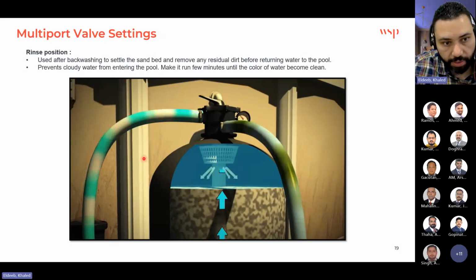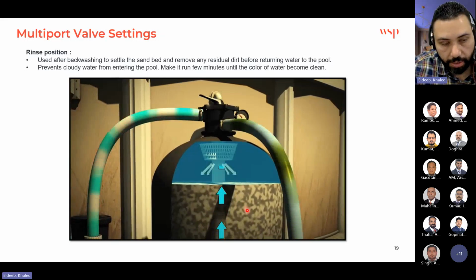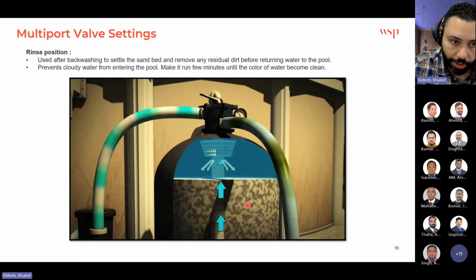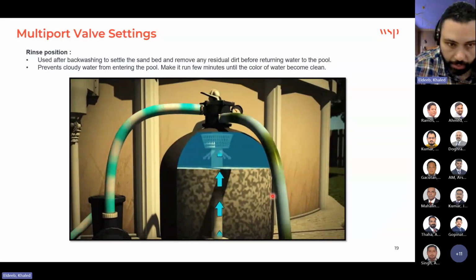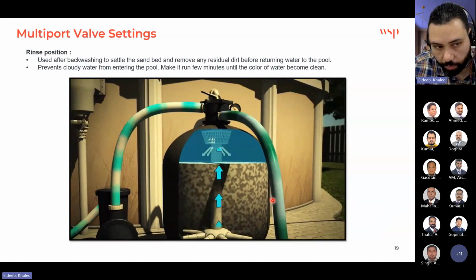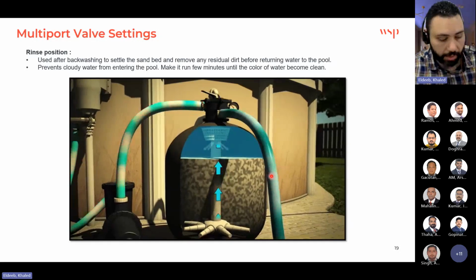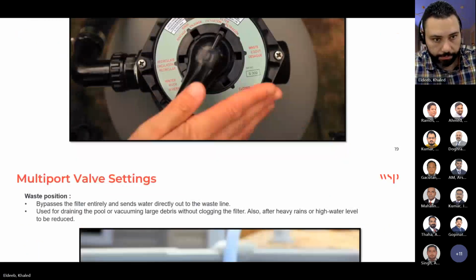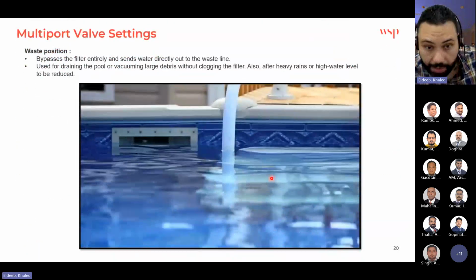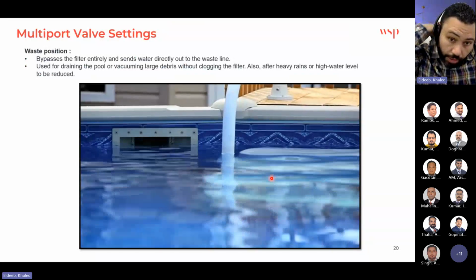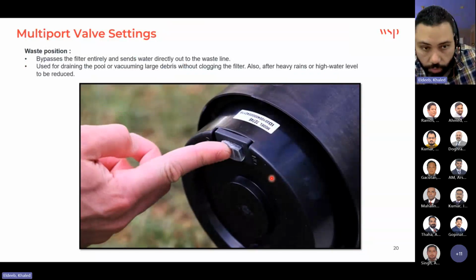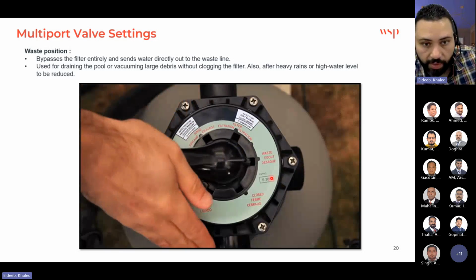So after finishing the backwash and rinsing, the pressure should go back to the original condition. As I said, if it is 10, and it becomes 15, after backwash it will go back to 10 again, and so on. That's why the resistance of this filter is very dependent on the condition. So we normally take it like a half bar, 5 meters.